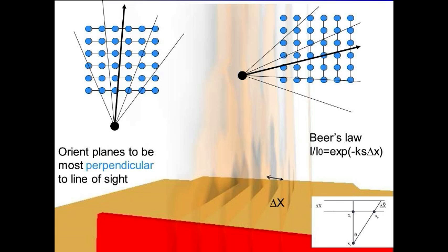Now, this is just an illustration, a schematic of how I'm solving the smoke now. You never see this view in Smokeview because, first, the way I'm drawing the smoke is I'm drawing a series of parallel planes, each plane corresponding to a grid plane that you're solving in your FDS simulation.